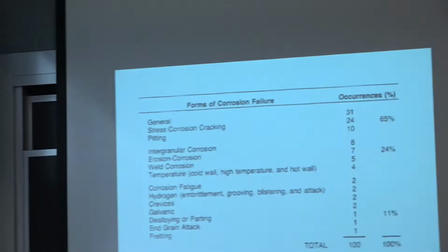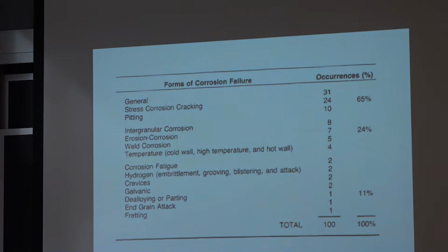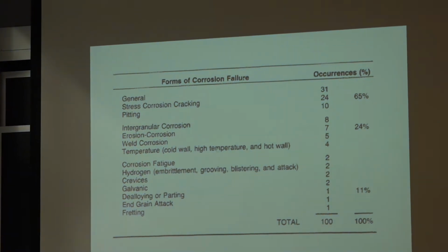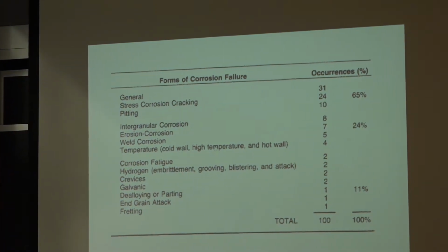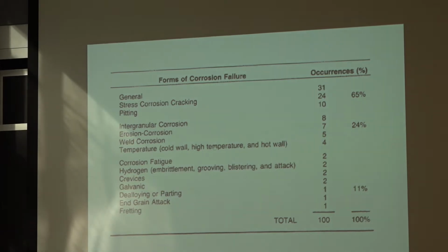Stress corrosion cracking is important in industrial applications. It's the reason why we have so many categories of stainless steel, for example. Some of them will be susceptible to stress corrosion cracking in certain environments, some others aren't. And then you can also think that there are industrial applications where regular steel is just way better because it doesn't have the same issues as stainless steel as far as stress corrosion cracking.